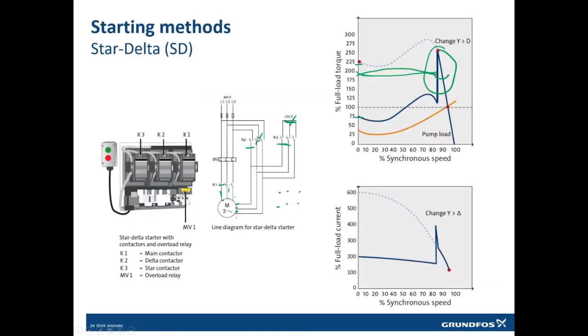It is done with the help of these contactors, these electrical devices, which act like electrical switches. They do this job automatically. So first, when you click this green button, what will happen? Contactors K1 and K3 will close. What will happen? The 380 will be connected in star.